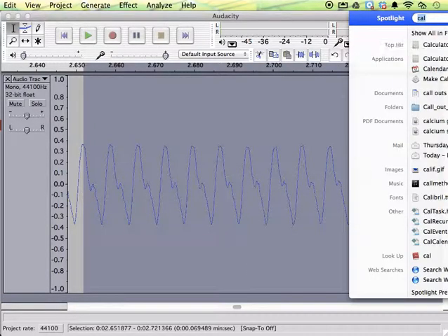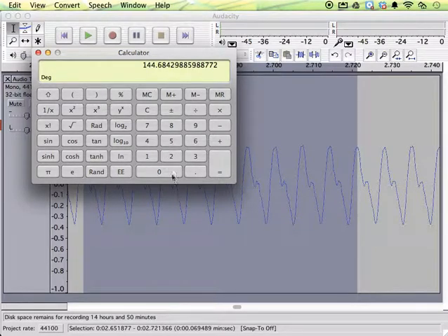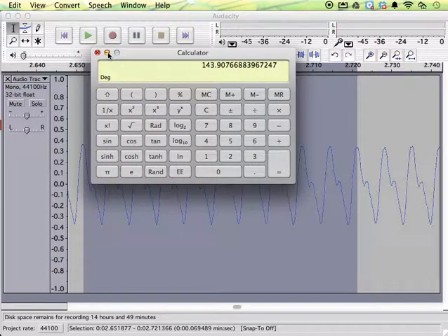So again, if we look at the calculation, we have 0.069489 divided by 10 to give the time for one waveform, invert to get the frequency, which is about 144 hertz. So there are minor differences, but we're talking about a waveform with a frequency of about 144 hertz.